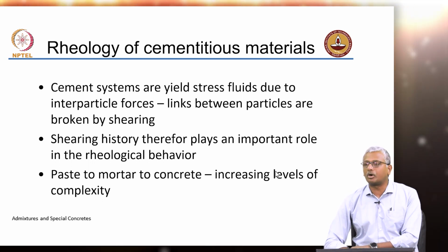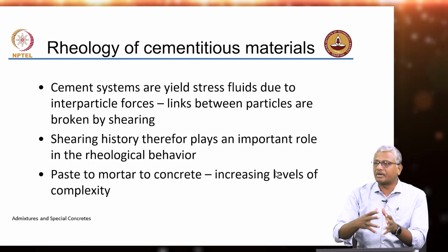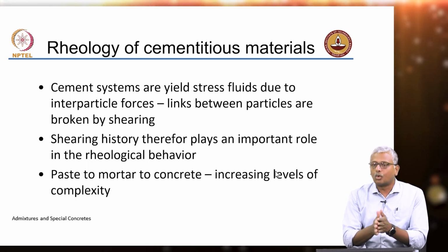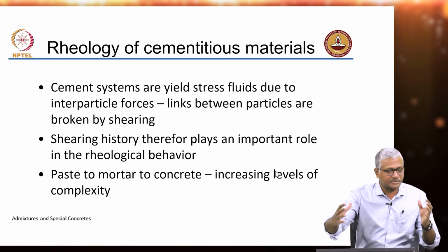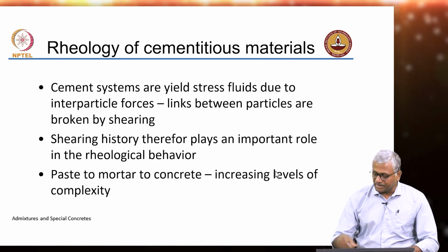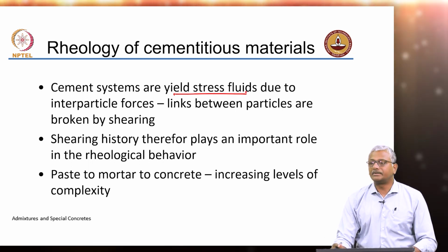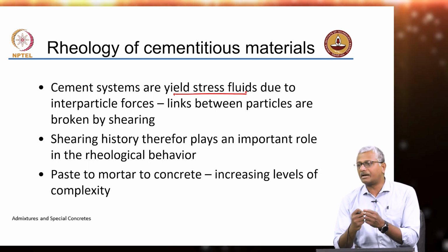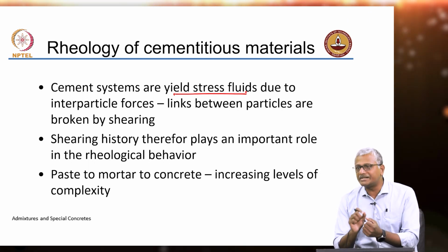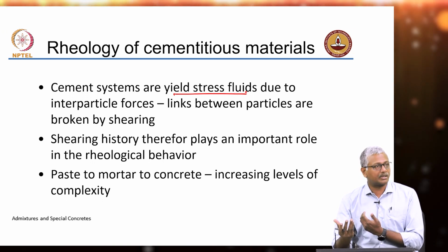We do that in normal concrete with the help of vibration. We pour concrete into the formwork, we vibrate. Vibration at high frequencies tends to overcome the initial internal buildup of the concrete and causes it to start flowing. So, we call such systems yield stress fluids. There are interparticle forces that cause the material to be very stable unless you apply a shear that is high enough to overcome this interparticle force.